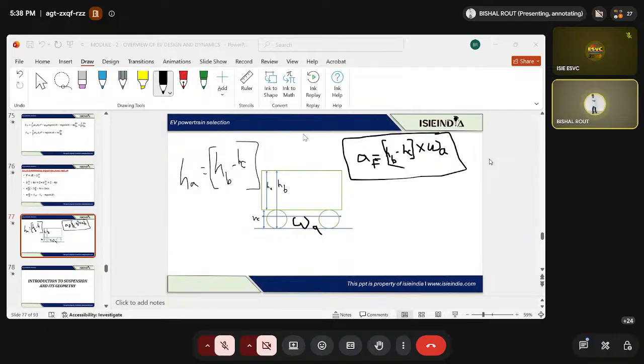You can see these values from behind, from the back. These are nothing but called a force. You can see this is the frontal area of the vehicle, this is the drag coefficient, this is the mass air density, this is half, this is 0.5, this is the velocity square, right? Now this is nothing but mass times dv upon dt. This is how the differential equation is being solved, right? This is nothing but the force I am giving.